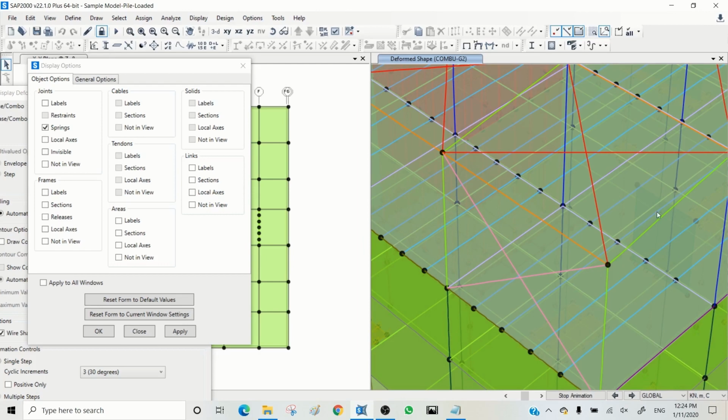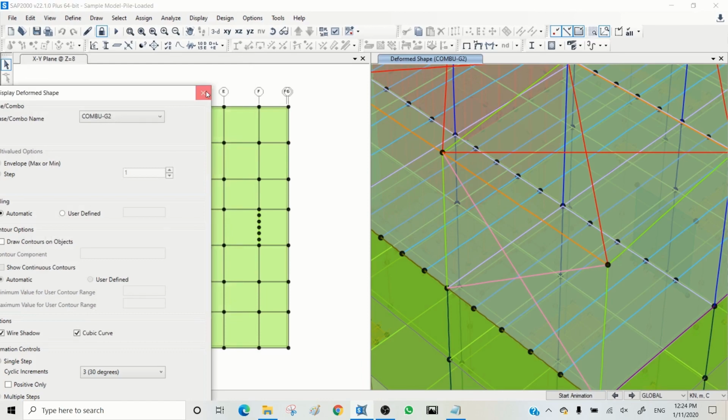That level of displacement doesn't show you this wall is moving, but you saw it in modal. So the combination of modal and displacement of different loads can give you an idea which element needs to be fixed. Okay, let's go back to the model and see what we need to do, and some other fine-tunings that I will show you to minimize the errors.